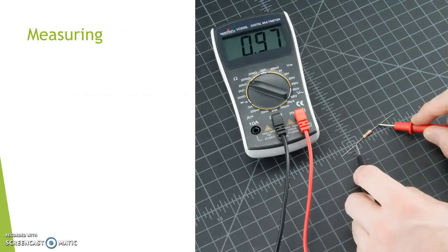Okay, and the measurement, you can measure, for example, the resistance of this resistor by just making sure the leads are on either side of the resistor. And most multimeters have ranges, and so if you see 0, you can go ahead and change that to a smaller value for resistance.